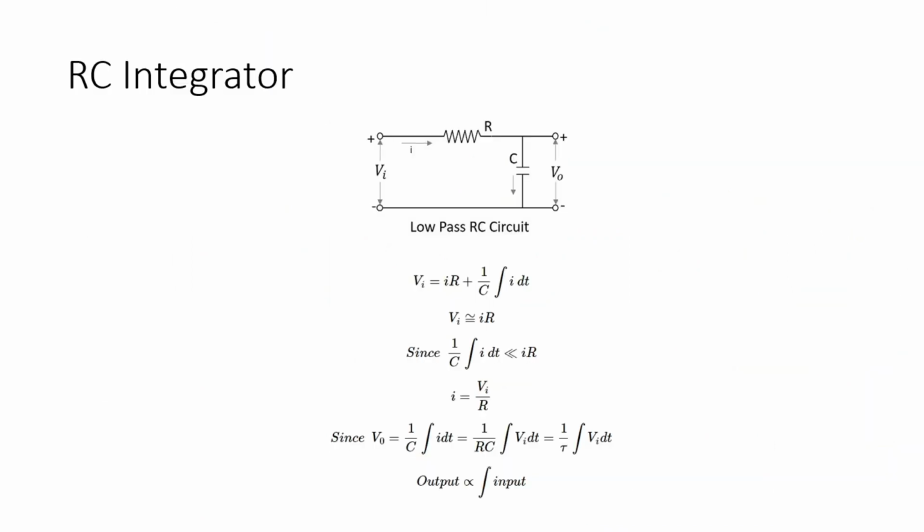So as we have seen that the integrator acts as a low pass filter, the simplest real world implementation is through an RC integrator, which consists of one resistor and one capacitor. As you are aware, the capacitor acts as an accumulator of charge or an accumulator of voltage. And this is exactly the purpose of the accumulator that leads to the integration action. So all the integration signs that you're seeing here essentially are because the capacitor has the property to accumulate voltages. Now, how fast or how slow that is done is decided by the values of these two components, R and C.